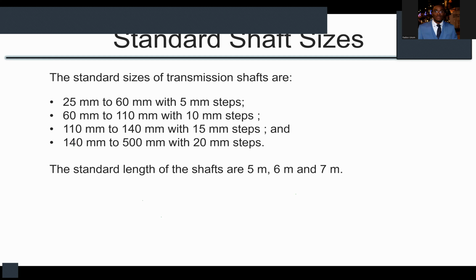Okay, so with 34.5, you are asked to choose the next available standard shaft size above your calculation. So I will choose 35. Now, what if my calculation gave me 30.235? Somebody might say, let's round it down. No.